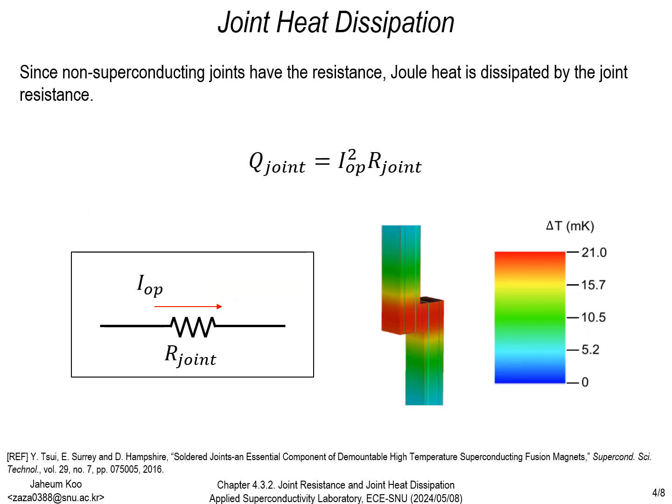During the process of joining superconducting wires, a small amount of resistance typically develops at the joints. This resistance is a significant source of concern, as it can lead to heating issues. Many of the problems associated with superconducting magnets originate from this very aspect of the joint process or from the heat generated at these joints.